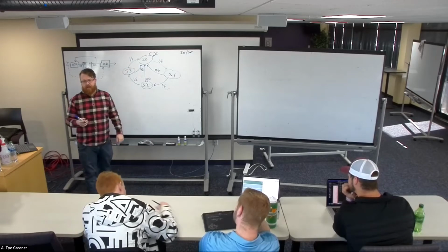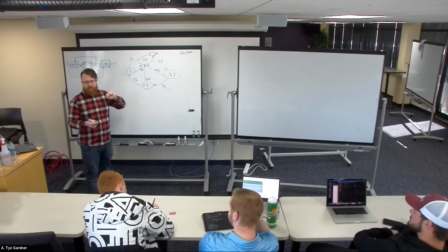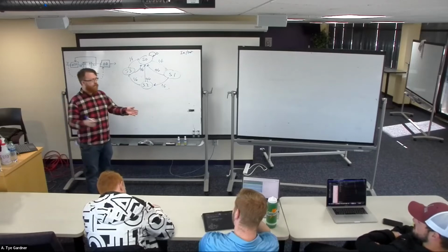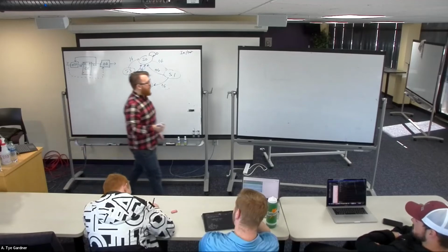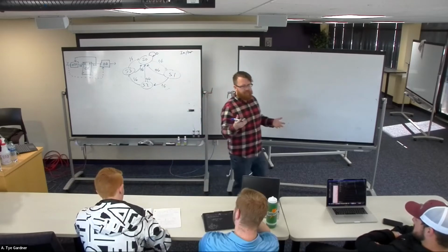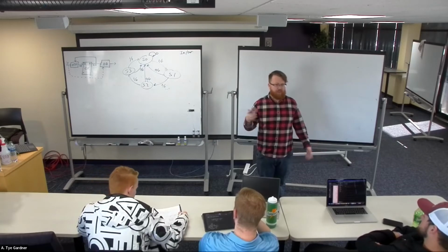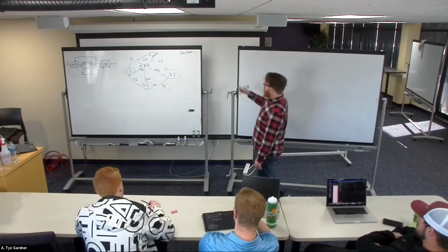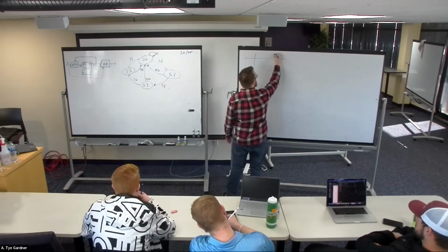So a 3 input AND gate, because how many bits do I need to represent all of my states? 2, because 2 to the 2 gives me 4 choices, which is enough. You don't really have to have that memorized, because we can just draw a truth table and start assigning states. Because what do we do next if I'm designing the circuit? Draw a truth table. We really call this the state transition table or the state machine table, the SM table, either one, right? Because we want to know where am I and where do I go, so that I can start assigning binary values to things, which is what we know how to work with.